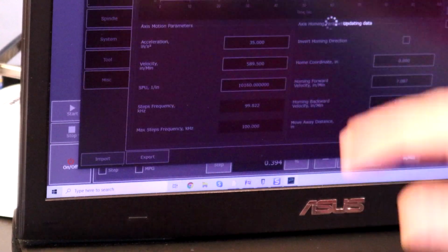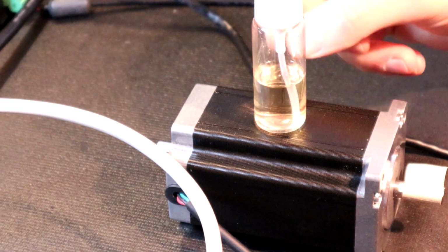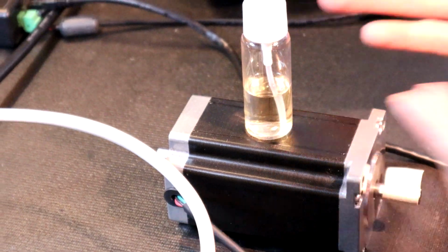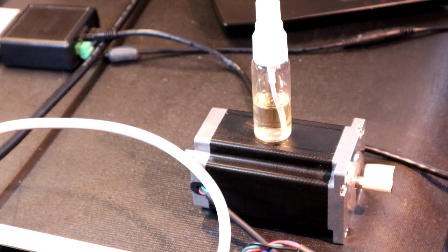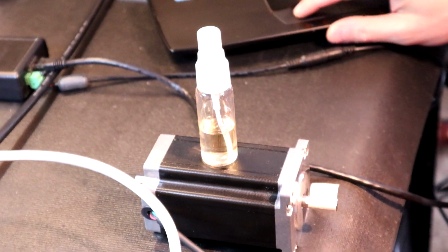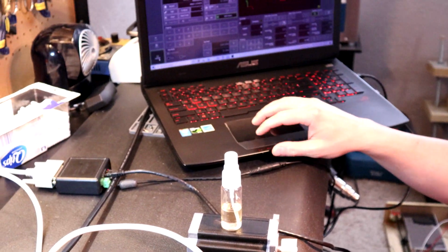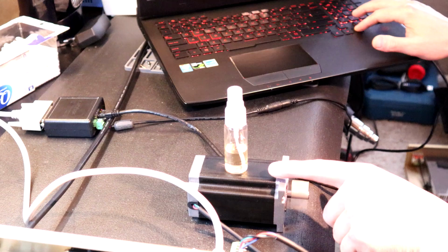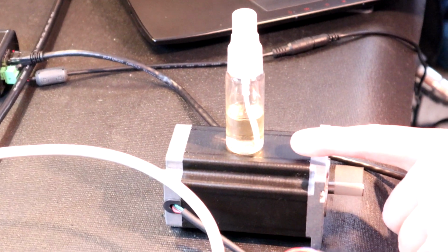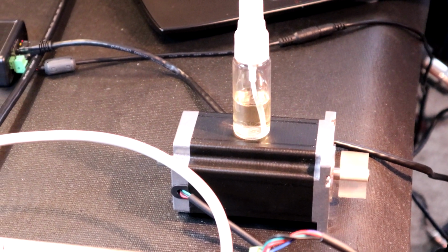At that same speed, I'm going to put some container of water. This is always a fun test to do because the water will show you definitively what kind of force is being exerted through the motor and also come over here as resonance. And that'll give you a visualization as far as what excess force is playing on the motor and also on your chassis. So check this out. We're going to go apply, let the data update, turn on our system. Now you'll see a big difference. You'll notice a slight jar in the motor as she's coming to a brake. We're going to accelerate and then come down, and then it stops. As that motor is moving though, you see nothing.